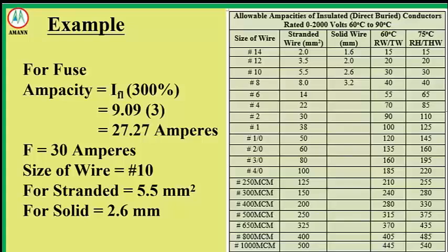This wire size is chosen to handle the increased fuse rating safely, reducing the risk of overheating and voltage drop. Proper fuse and wire sizing are essential to maintain electrical safety, preventing circuit damage, and ensuring compliance with electrical code standards. That's all for this video.